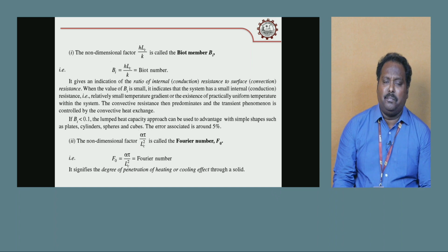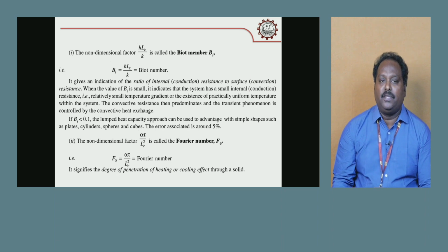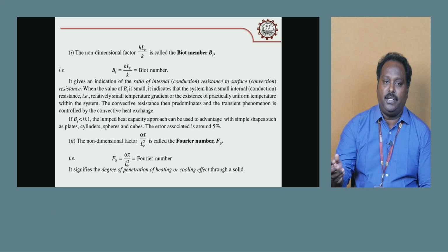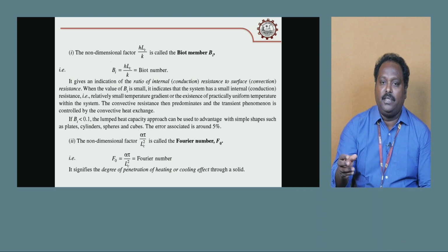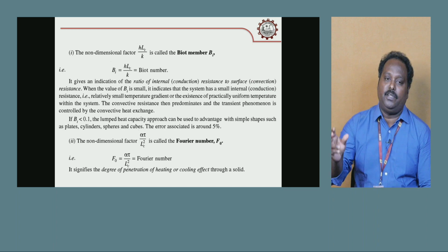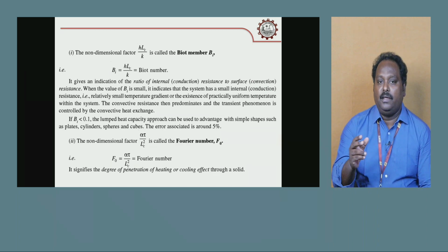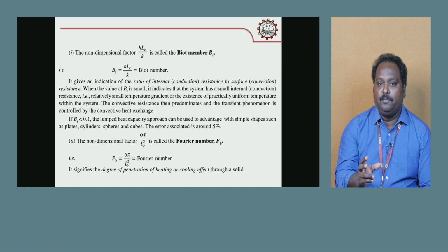So this lumped system can be applicable for cooling of solids as well as heating of solids. When you take a watermelon from the refrigerator and leave it on the table, the temperature of the watermelon is less than the atmosphere. After a certain period, slowly the heat transfer takes place from the atmosphere to the watermelon, so the watermelon temperature slowly increases with respect to time. So this is also unsteady state heat conduction. It is called Newtonian heating.